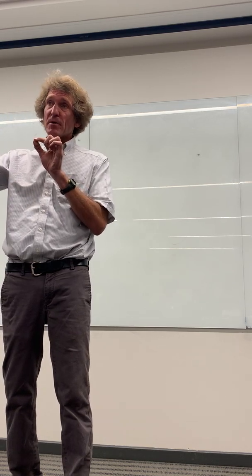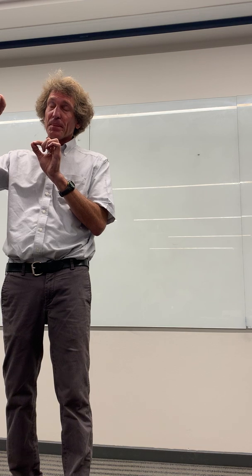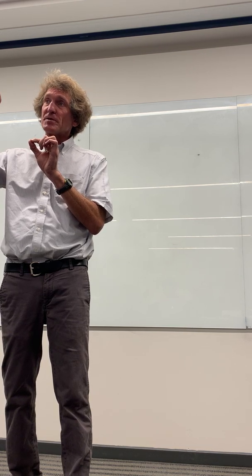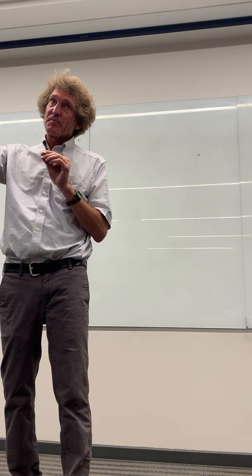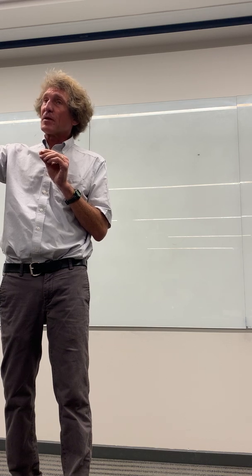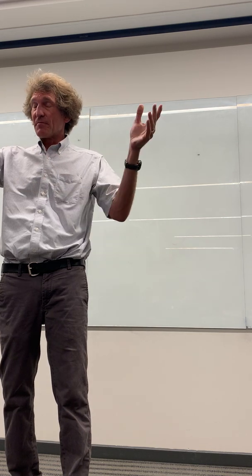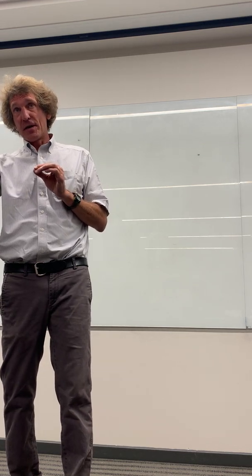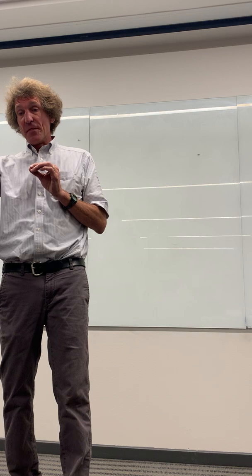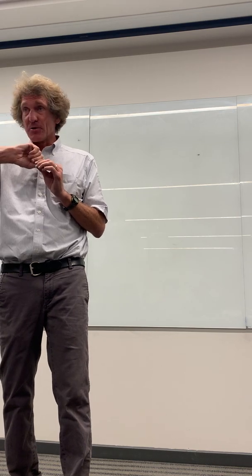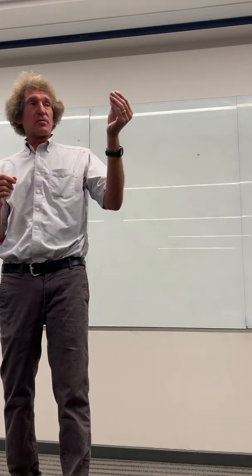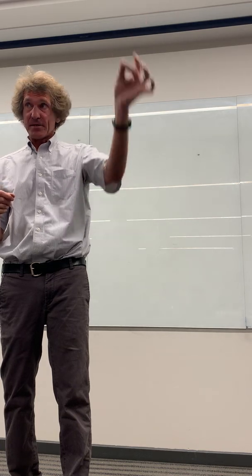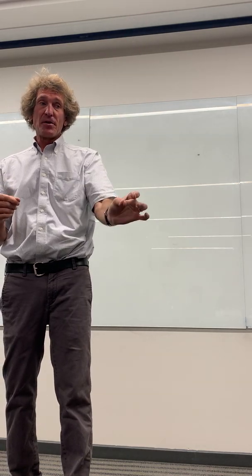And here's the thing, as soon as you start a breakdown, think of lightning, because I did my doctoral work with lightning. As soon as it starts, it's almost always self-sustaining if there's enough charge there. This is called a step leader. As the ionization starts, it starts breaking down in front of that, and it's a runaway train if there's enough energy, and it'll just arc over to wherever the negative charge is. So it starts at the positive. And then as soon as it's done, it's like a short, and then the current just goes nuts. Lightning always has a step leader, a very faint, low amount of current, and as soon as that step leader connects from the cloud's charge center to the Earth, then that large flash comes, and that's the flashover.